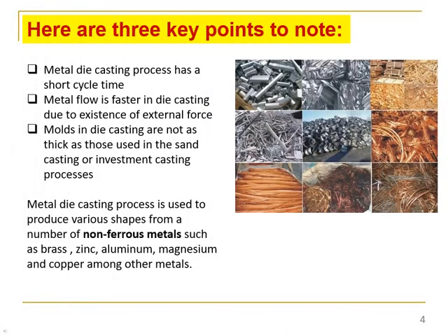Here are 3 key points to note. Metal die casting process has a short cycle time. Metal flow is faster in die casting due to the existence of external force. Molds in die casting are not as thick as those used in the sand casting or investment casting processes.